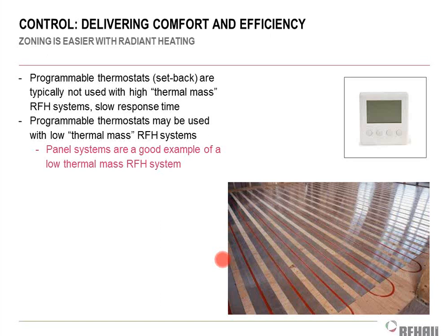With the radiant floor, you're heating up the concrete, this big giant mass, and that mass, by the way, is radiating to all your shelves and products and everything like that, and they become re-radiators. So when I open up the dock door, I don't lose that heat hardly at all. So it works really well. That slow response helps us sometimes, but it does not help us if we were thinking about using a programmable stat.